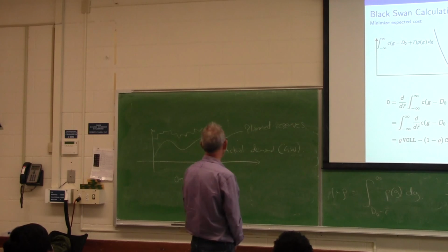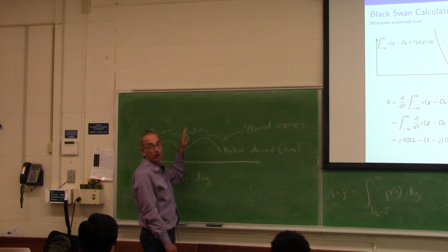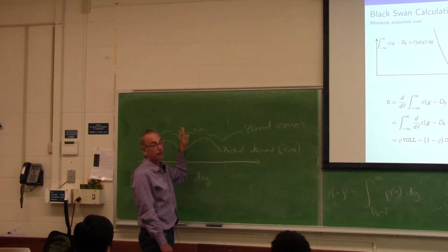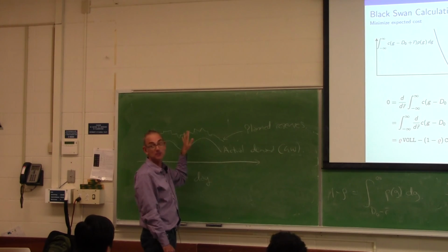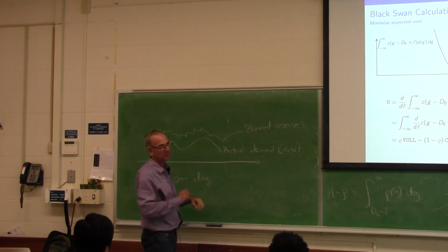When this really gets low, if it goes to 5% instead of 12, they have scarcity pricing in parts of the country, especially in Texas. So prices go to $9,000 a megawatt hour, that's scarcity pricing. They just make the price shoot up when this gets low. And the closer this gets to zero, the more they make those prices go up. And it'll hit that $9,000 ceiling. And PJM, California ISO, they're all into this scarcity pricing to make the prices shoot up to massive values whenever this gets small. Why?